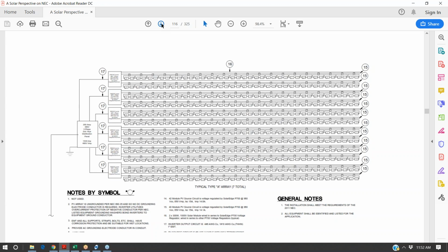It's hot down in the south, so I'm sure air conditioning was going. She's like, I know I'm not supposed to use both my dryers at the same time, but I did, and the breaker tripped. Great. We know why the breaker tripped. Reset the breaker. You're going to be fine. It's when you don't know why the breaker trips that there's an electrical issue that needs to be diagnosed.